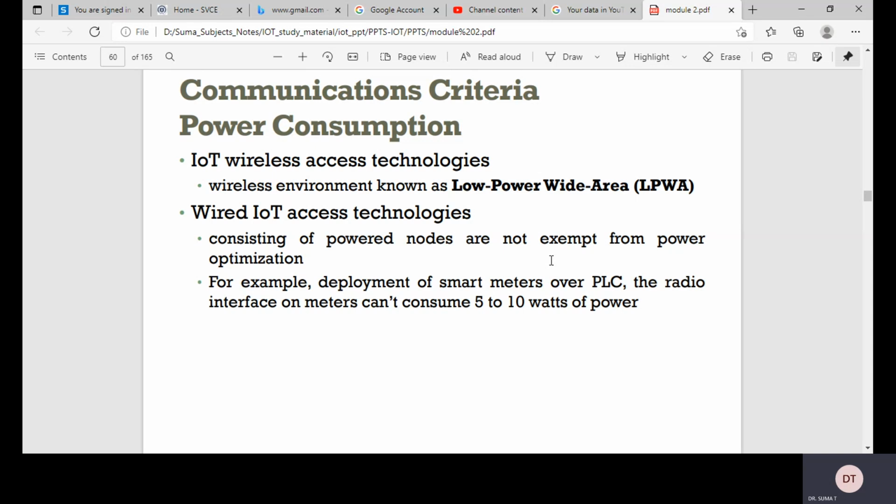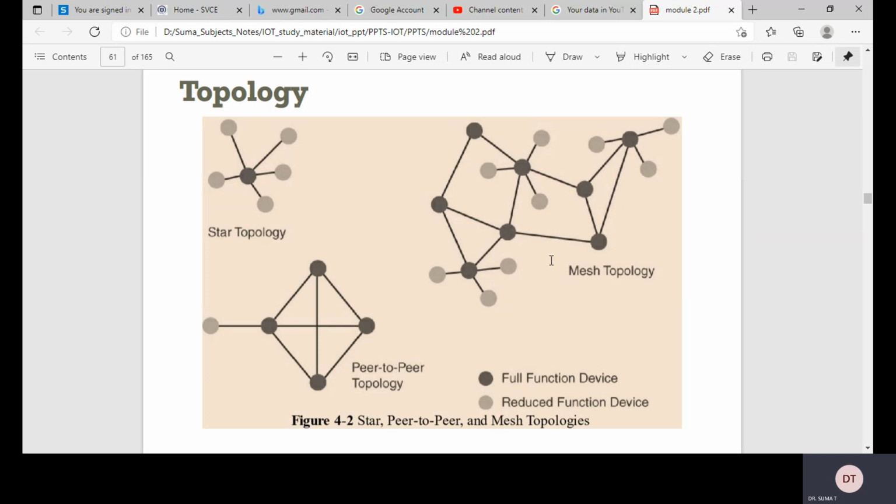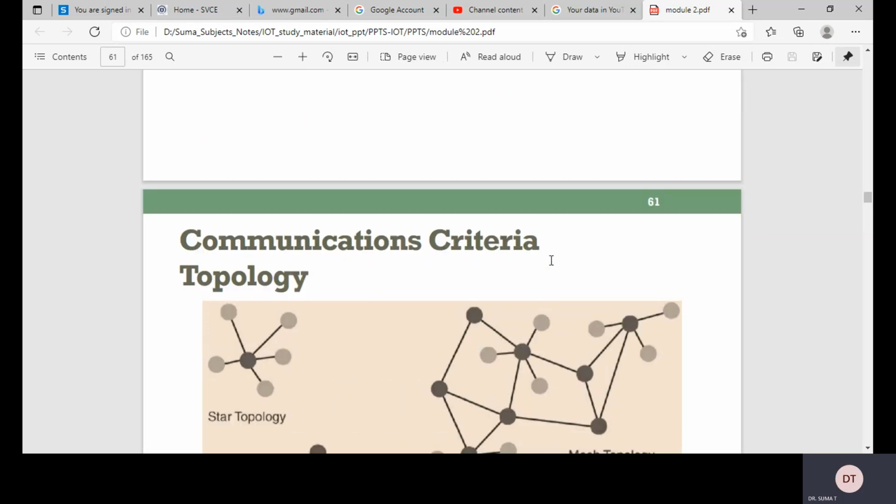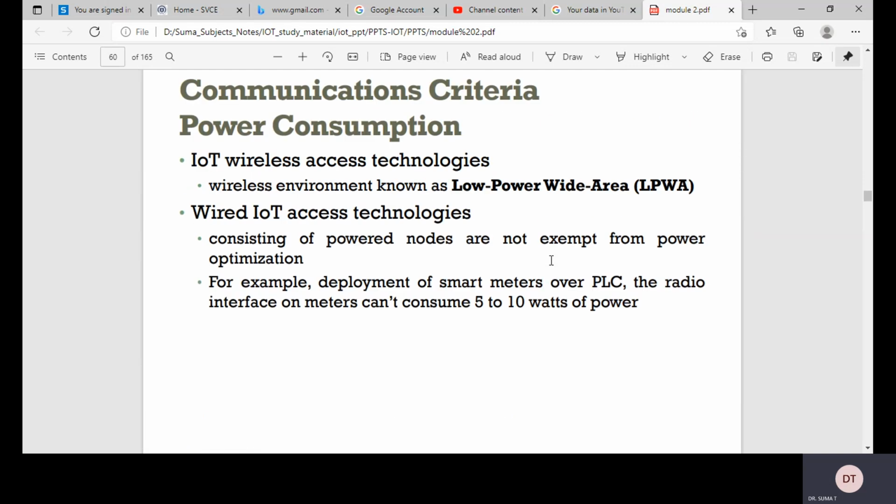The sub-gigahertz frequency bands allow greater distances between the devices. These bands have better ability than the 2.4 gigahertz ISM band to penetrate building infrastructure or go around obstacles while keeping transmit power within the regulations. The disadvantage of sub-gigahertz frequency, however, is the lower rate of data delivery compared to higher frequencies.